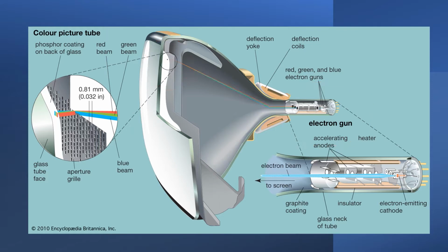Now importantly, these monitors have little deflector coils on the side, and they generate a magnetic field that can bend the electron beam. So, with some clever electronics, we can sweep the electron beam all over the display. We'd start at the upper left, move to the upper right, then we'd quickly scoot back to the left and down a little. This is one scan line, and we'd repeat this pattern from top to bottom. This type of scan is called a raster scan.